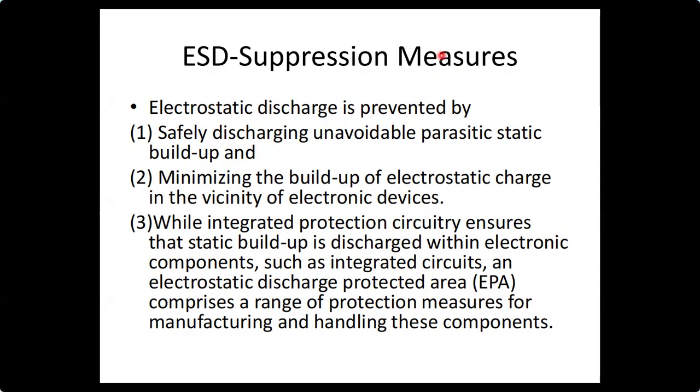Every engineer should be trained in how to suppress ESD in the workplace. I want to tell you: short trace length to protective components, ground planes and the sensitive areas, controlled impedance path, HBM, human body model, and machine models for component level testing.